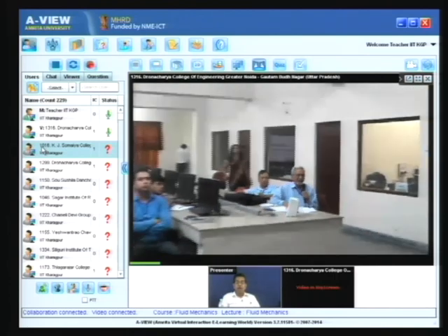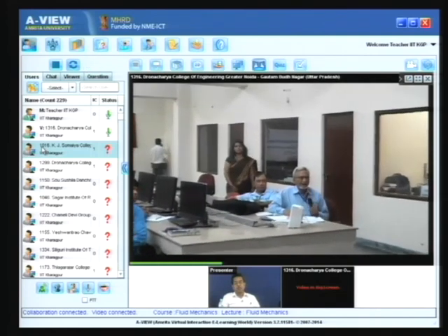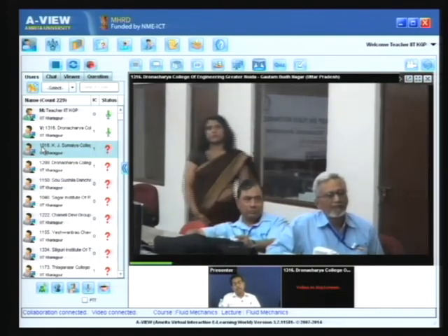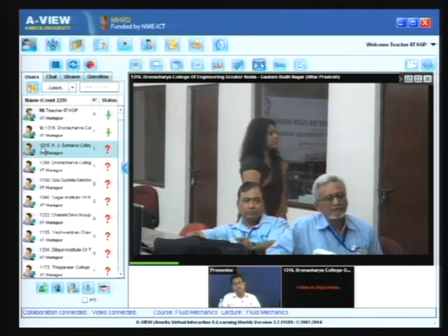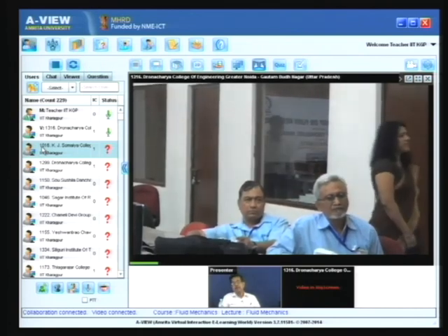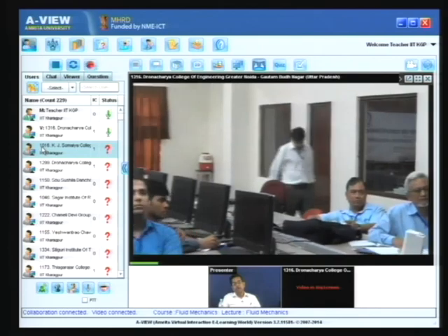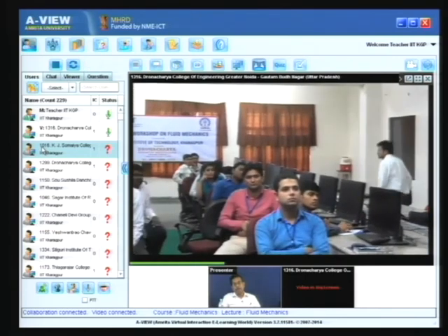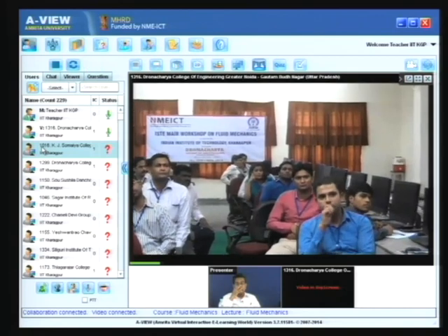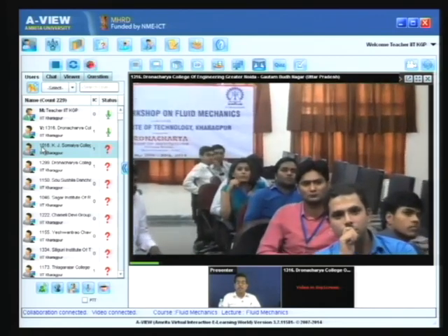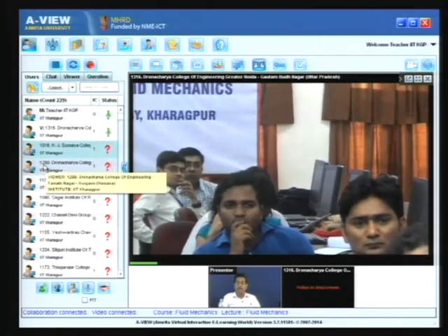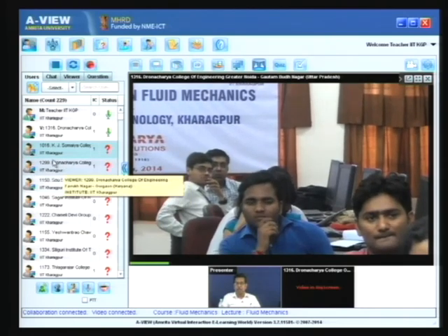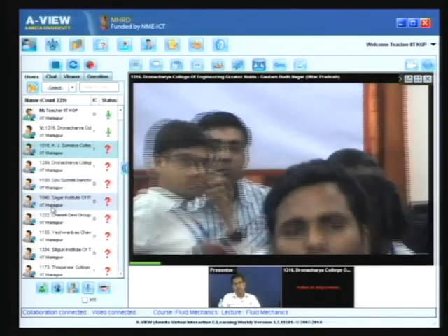No, model creation. You see, first of all you have to make a geometrical model, and first of all you have to find out the non-dimensional parameters. Just a simple example: let us find out the model of a ship. The resistance of a ship depends on the Froude number, Reynolds number and its non-dimensional geometrical parameters, because if you want to find out the power of a ship, you have to find out the resistive force.